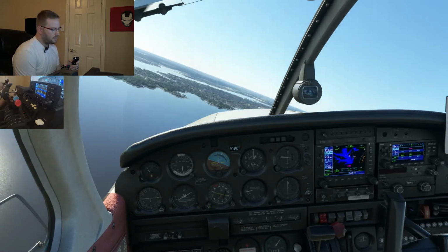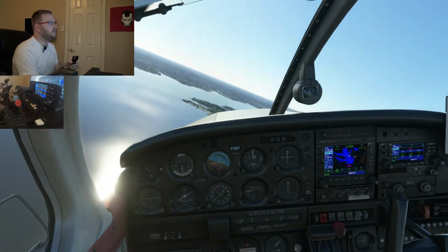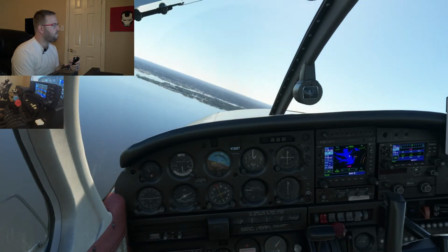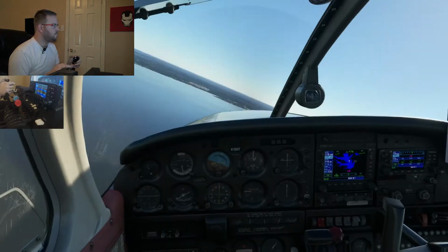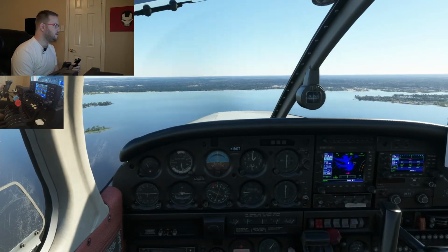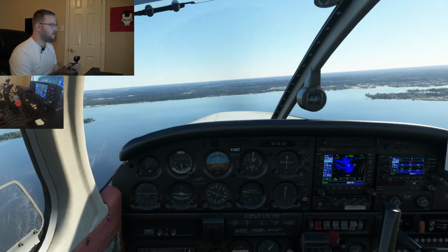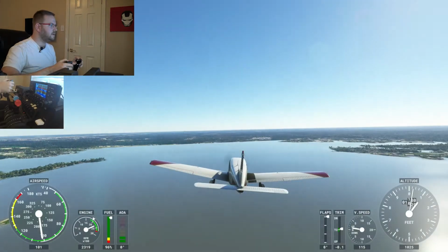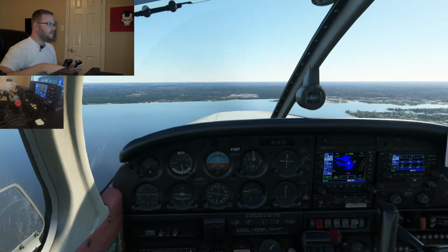We also make sure we're pretty visible for the maneuver. So the landing light on, taxi light on, turn on our fuel pump because we're low to the ground. Let's just keep our approach checklist in as well for safety. Okay. So now we are coming up on the island. There she blows. And we're going to be doing our turns around a point around the island. We're a little close to it, so this might be a little wonky. But let's do what we can, okay?